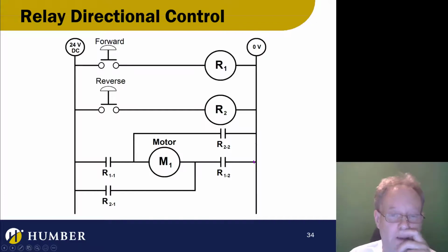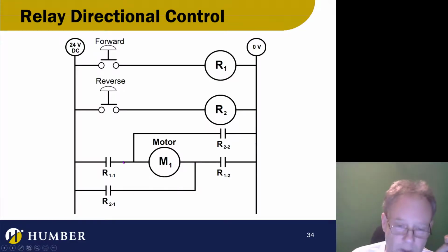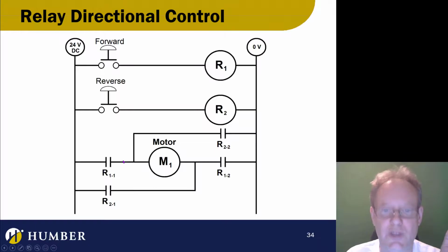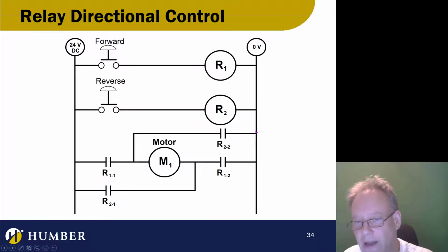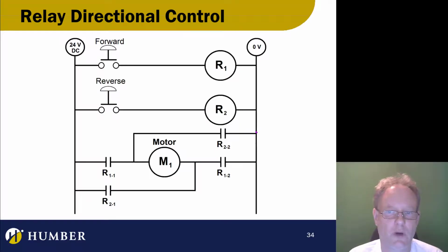Okay, that's fine. Now, if I release that button, and I close this button, then this is open, that's open. This becomes closed, that becomes closed. Watch this, the current goes here, it goes through the motor this way, polarity flip, sweet, and then it goes this way and back there. So I've just controlled the motor. Yeah, so in both directions.